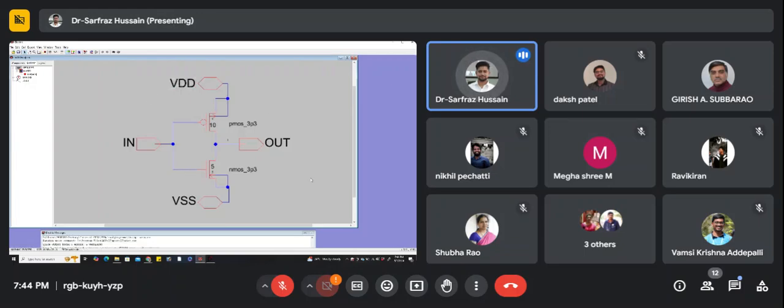So this is how we do the circuit simulation. We first make the schematic in the Electric software. We generate the inverter.spi file. That SPI file we can use to run the simulation using the LTspice tool.